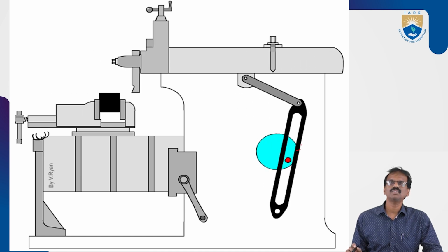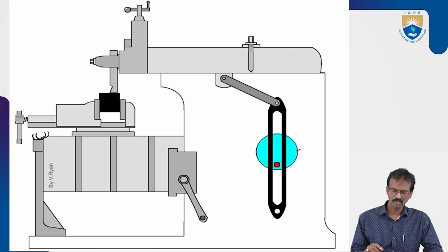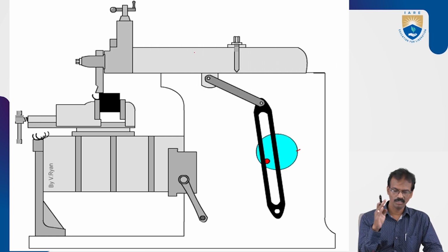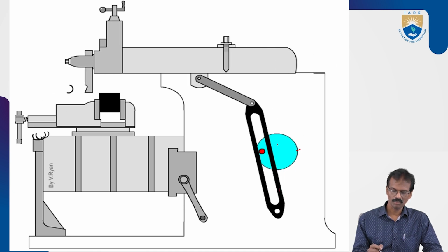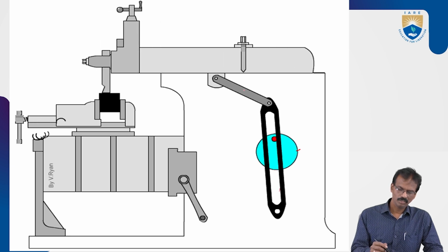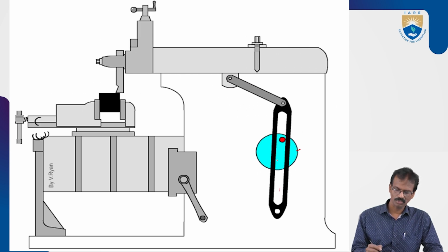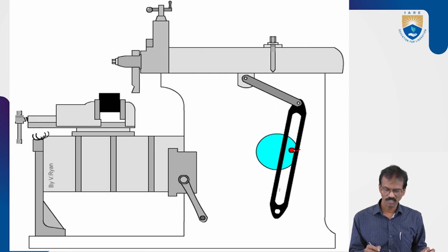So here, this is the engine that rotates. This rotary motion is converted into reciprocating motion by the lever, a hollow-type lever and clamp. It has two jaws. One is attached to the ram, another is fixed with the pinion, which is mounted on this gear.